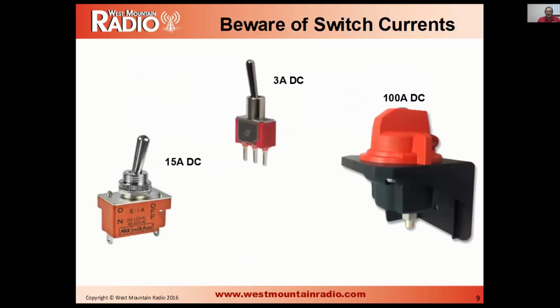Switches. Be very careful with switches if you're using them in a ham radio situation. Most switches aren't anywhere near the amount of current that you're going to need. Look at the DC rating, not the AC rating on the switches. I've got a 100 amp switch there on the right, just so you can see what it looks like. But most of your other switches are not going to have nearly enough current handling for amateur radio use.